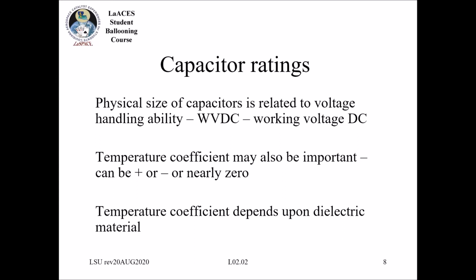I'll also say that some of these guys have a bias in them that depending on what voltage they're operated at, the capacitance may decrease. It'll never be increased above whatever the actual value is, but it may decrease based on the voltage that's applied. So just another important point. And that's really important with the surface mount components more than the through-hole ones.